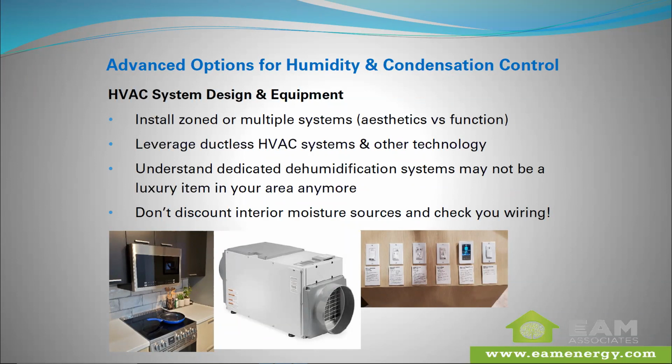Dehumidification systems as standalone: I totally agree with Michael that you should not just go to that as a first option. You should be able to take care of a lot of these issues with proper design, equipment selection, and installation. But that being said, we are finding that dedicated dehumidification systems, in many areas, ours included here in the Northeast, have always been viewed as a luxury item, and it may not be anymore, especially for your particular project and for what the end user is going to be expecting.